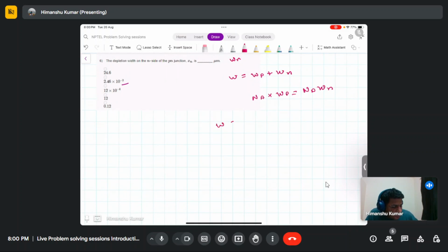So W will become Nd by Na Wn plus Wn, and this will become (Nd plus Na) by Na times Wn, and if you simplify, Wn will be Na by (Nd plus Na)